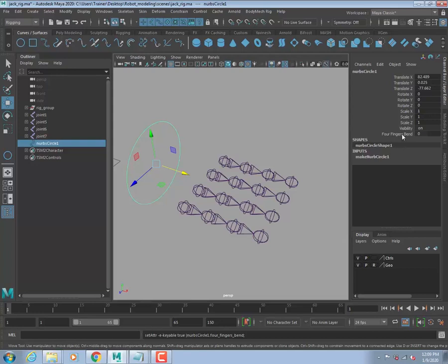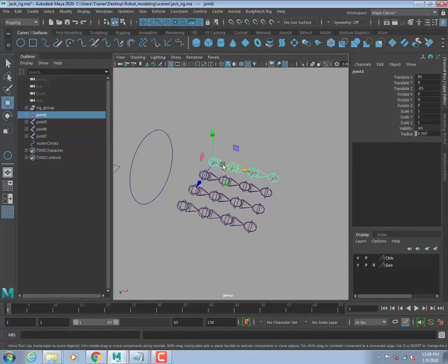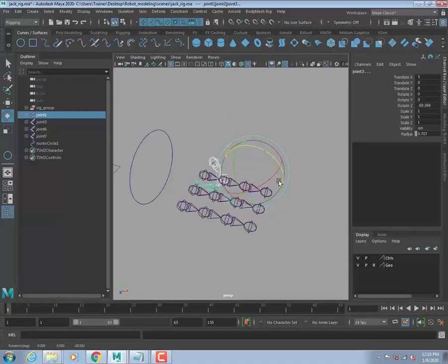The attribute is there, but it won't do anything. I can change the value, negative 10, positive 10, but it doesn't do anything because there is no other connection. So set it to default. Okay, and I need to find out what rotation I need to control. If I select these 3 fingers, this is rotate Z. Alright, rotate Z for all these objects.